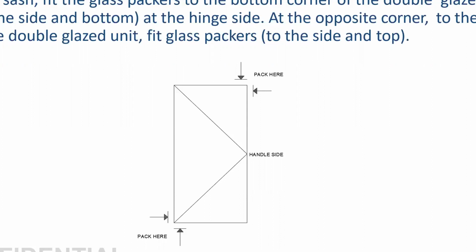He has to apply some silicone, paste it with the frame, and the glass, he has to remove that beading. He has to put that packer, he has to put the glass, and it will work.